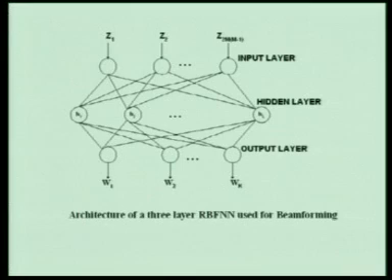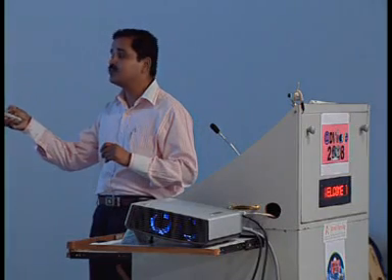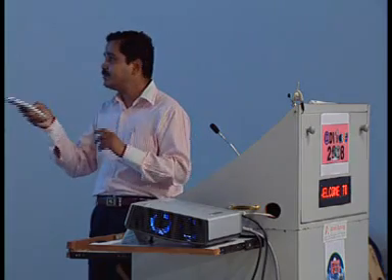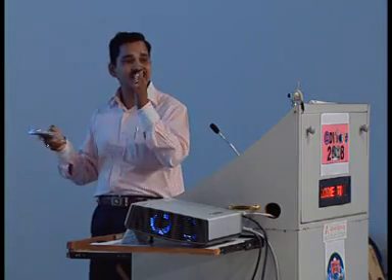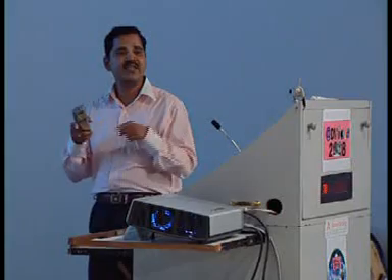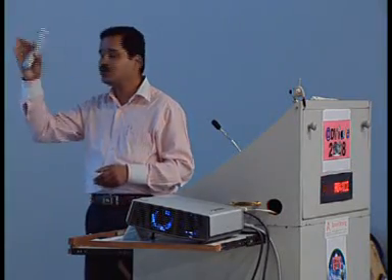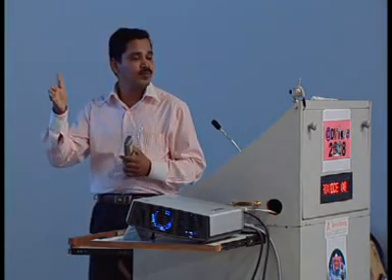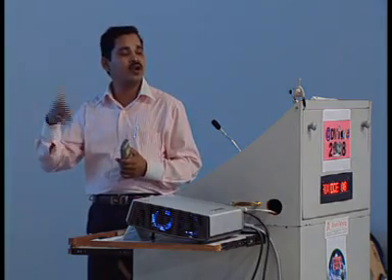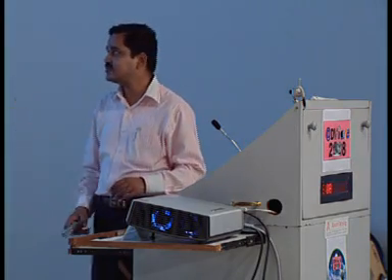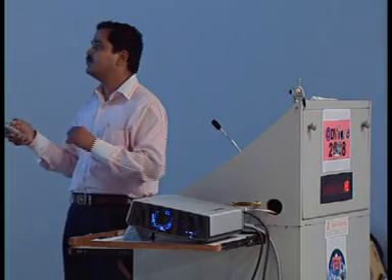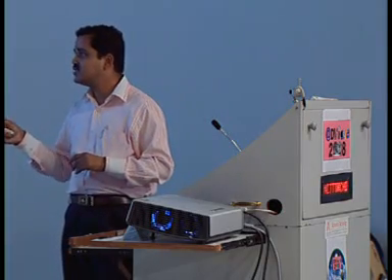Now in the beamforming phase, your output is the weight values, right? Because depending on the weight values, that means depending on the excitation to each of the elements on the array, your antenna will radiate in a specific direction, or it will give you a null in a specific direction. So in the second phase, you are actually finding out these weight values.